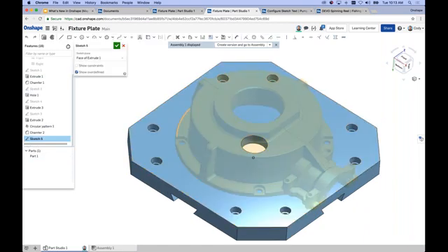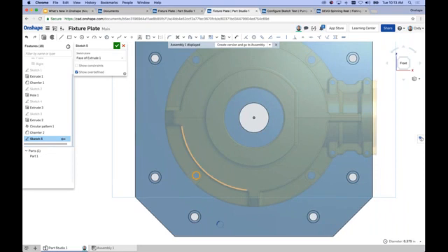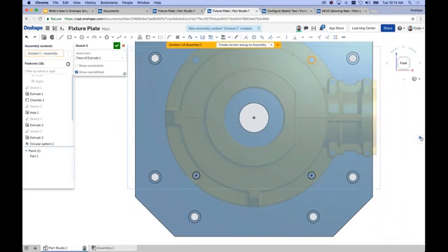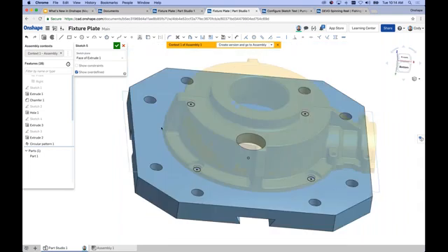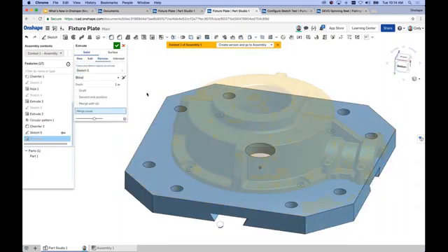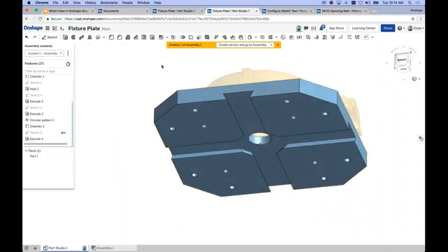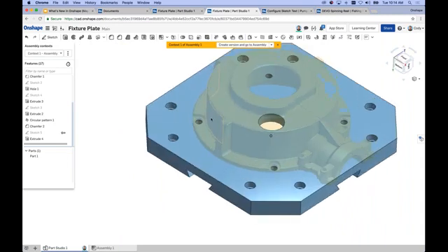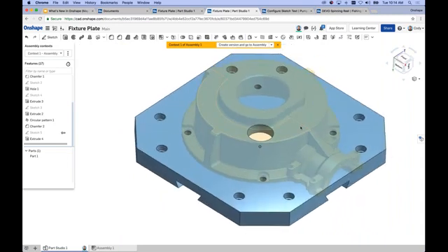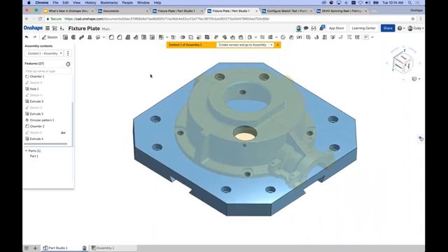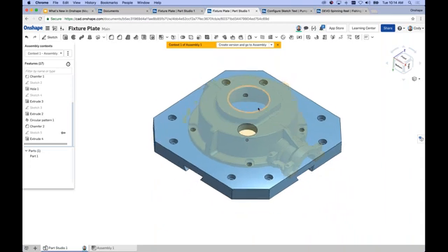So let's go ahead and start a sketch here and maybe convert a few edges, all right? Grab and convert a couple of edges here, and maybe just create some simple holes. Right, we'll go through all, okay. And so now we have a bolt pattern that matches this part, and this part came from a separate document, right? Now, I think this is most applicable in those kinds of scenarios where you have these separate projects, but you need one to be worked around another in a separate document.